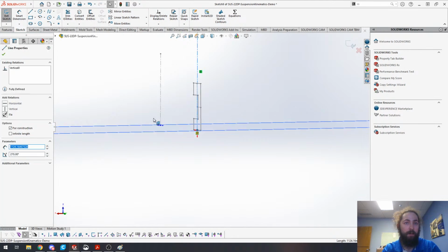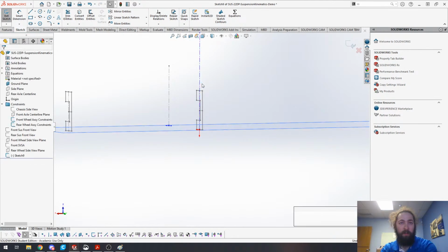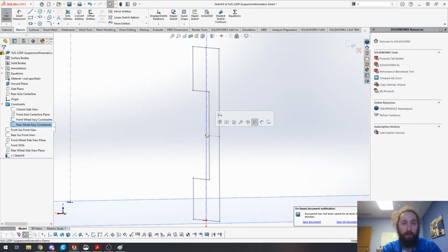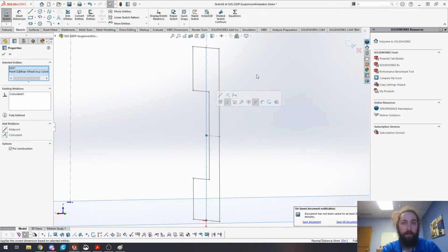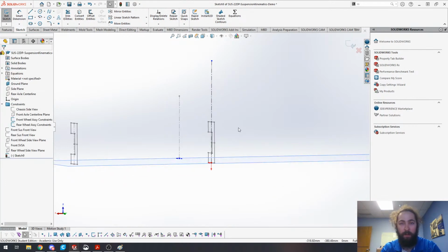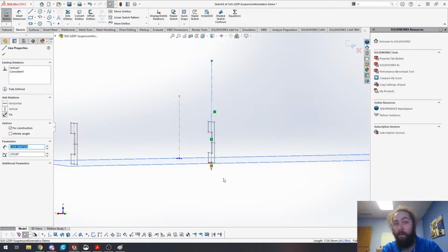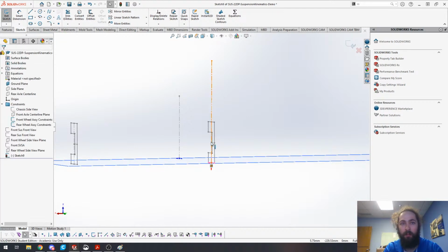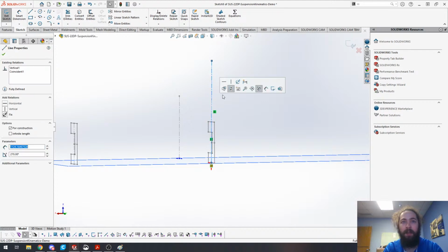And just to be extra sure that it's vertical, I'm going to make sure that that's coincident. Cool. And then you have to make it vertical. Everything should rebuild okay. If this doesn't rebuild, it means we have a problem, because in this case, we're technically over-constraining it. We have 2 points that are defining the line, and then we're also making sure that it's vertical. So just a little sanity check that we're building in for ourselves for later on.